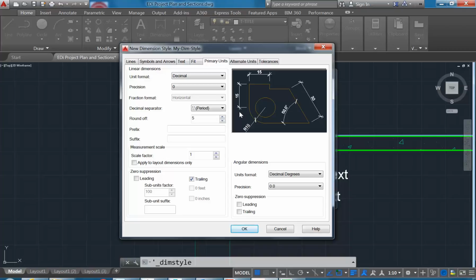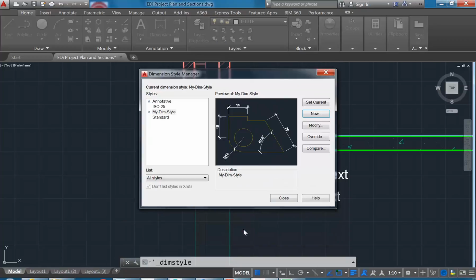Oh, that's just batch plot. Well, a couple of ways. You can do individual files and then combine them afterwards, but if you use batch plot, it'll do it all in this one. With batch plot, oh yeah, it's just on the main menu. So the secret is get one page set up properly, and then you can use batch plot with the same settings. I'll show that afterwards. Pretty straightforward. So, can you just go back to things and arrows?